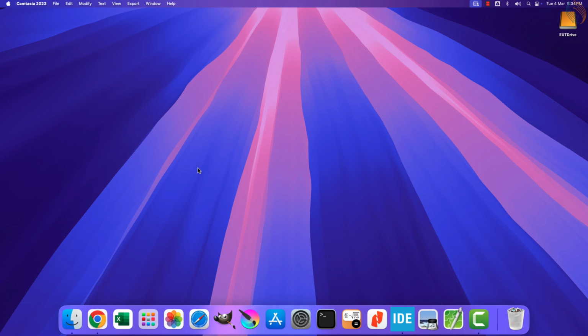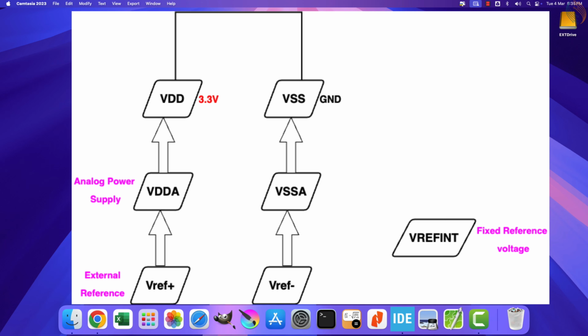We will also see the availability of the reference voltage pin on different STM32 dev boards, and even if the pin is available, how to actually make it useful in our application. I will demonstrate the measurements on 3 different dev boards, the Nucleo F446, Blue Pill F103, and the H750 based custom board.